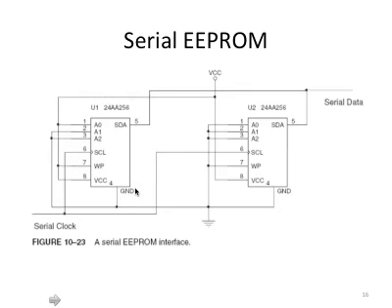The other signal I want you to pay attention to is this clock, the serial clock, and this serial data. The clock supplies a clock signal to drive the operation of this memory chip, and data is connected to the data line. Since we're talking about a serial connection, we only have 1 bit of data.